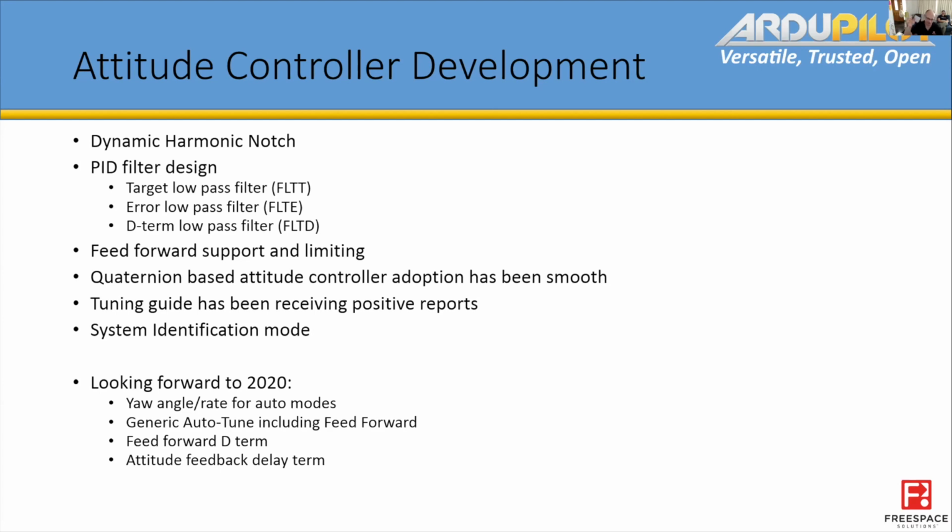I've got the algorithms already there for the most part, and I've got tuning methodologies that have been shown to work well, that can be adapted into auto tune for feed forward. But the bit that's beyond my personal programming skills is being able to point auto tune at a PID object, any PID object, and say, all right, this is what I want to tune now.